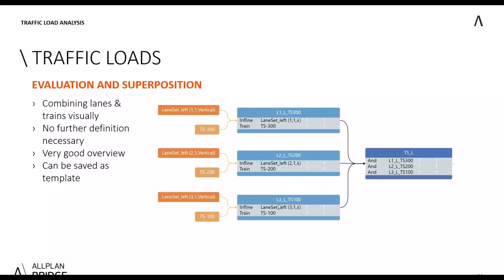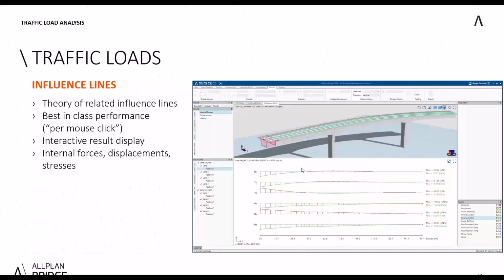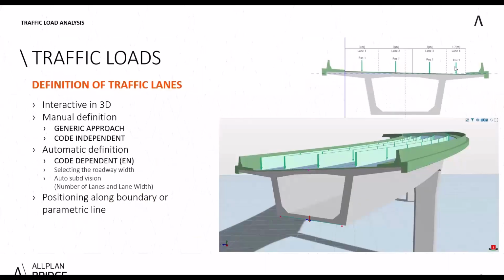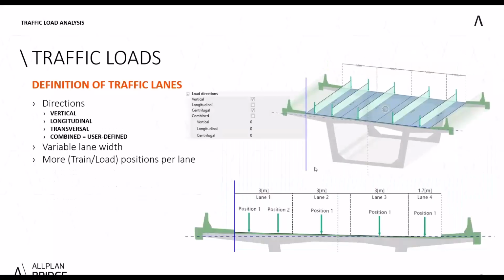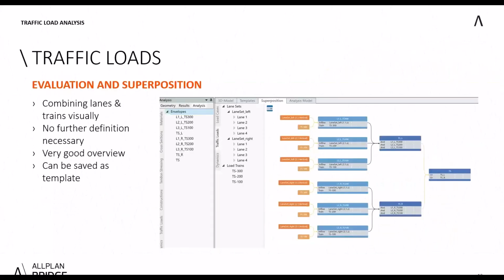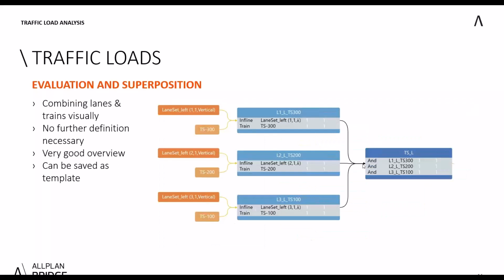And of course, they should not all be just added, right? Because let me just go back once more, because you can already imagine, of course, if for the anti-clockwise torsional moment, of course, I do not want to put this load on it because it will be favorable for it. So, of course, the user doesn't have to think in that way of it. He just superposes all the individual loads with the superposition rule and, which means the program will just check, because, of course, for the bending moment, he will only add the result if it's more unfavorable. So the last train, of course, would be added for the bending moment, but not for the torsional moments.